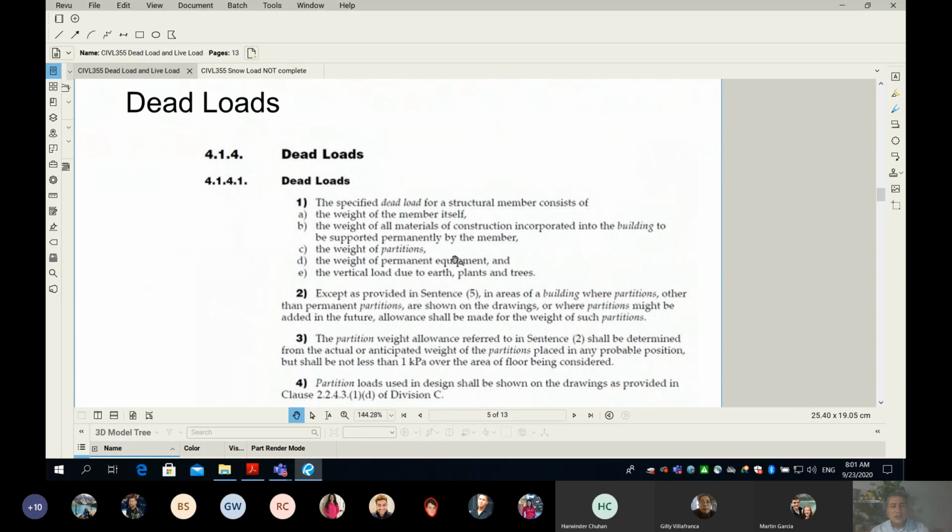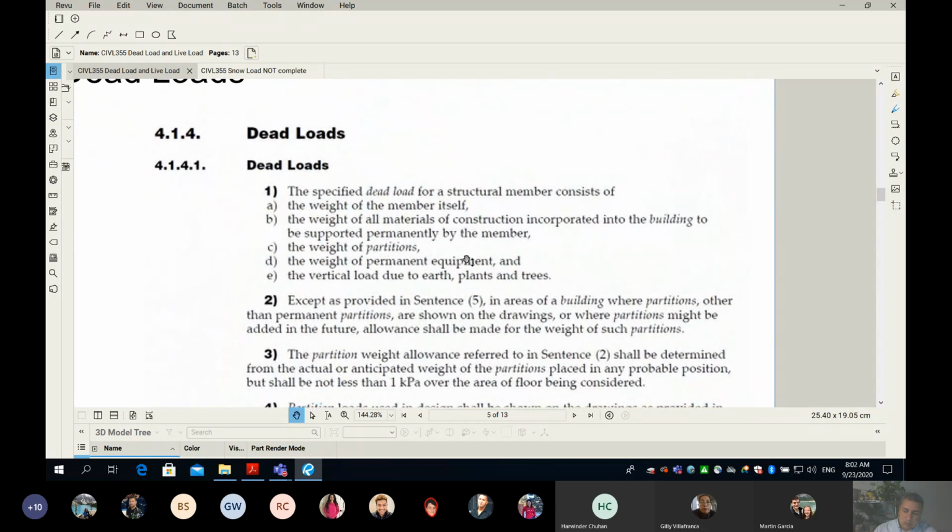Now, I guess the first thing is we need to set and define what makes a dead load. Because sometimes, trust me, you think it's easy and straightforward, and this is dead load. For example, if you have a building and this building has a podium, people in summer go outside and enjoy, and on this podium there are barbecues and some planters for plants. What do we consider those planters? Do we consider them as live load or dead load?